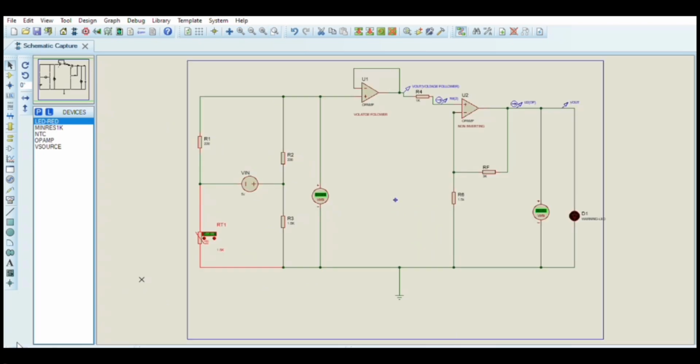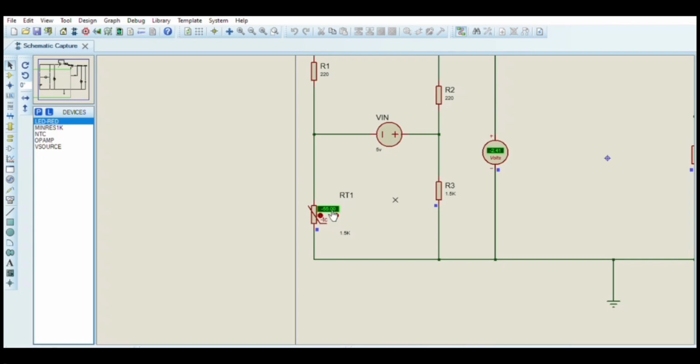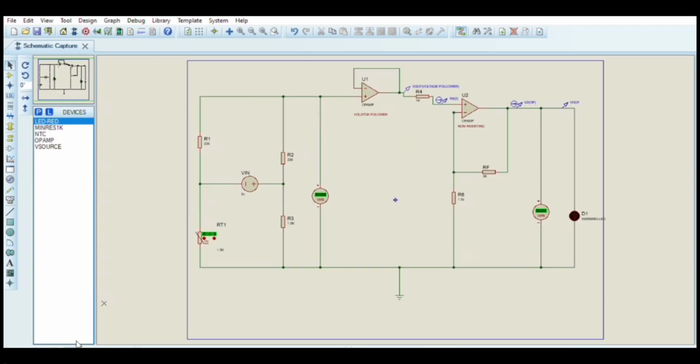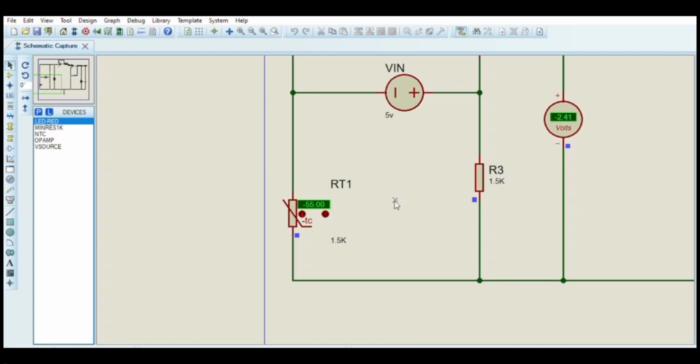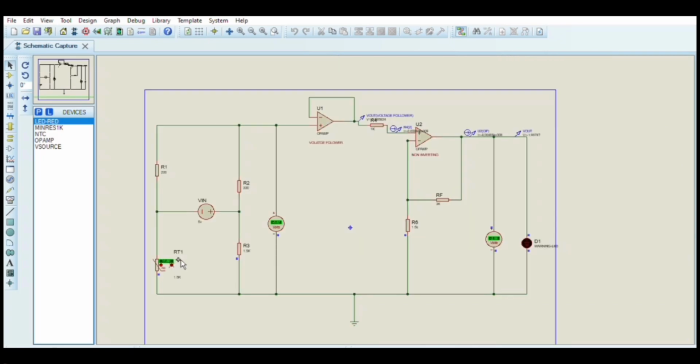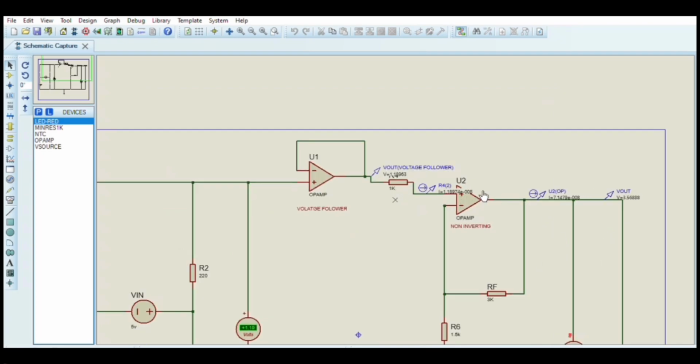When we run the program, the meter that we set starts at negative 55 degree, and you can see that when the temperature goes up to 52 degree, the warning LED will turn on. From 52 the LED will stay on until 400 degree, and then the Vout is 1.8.